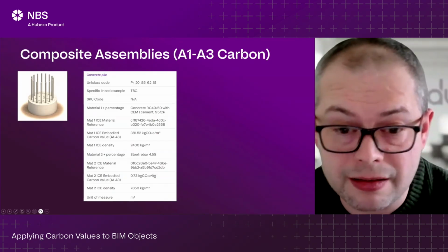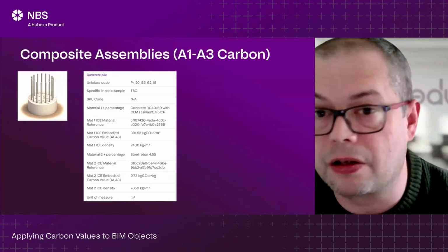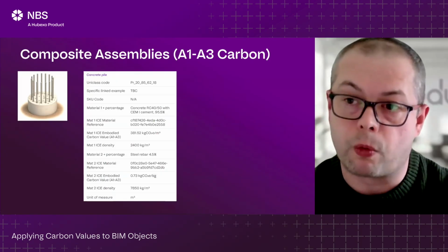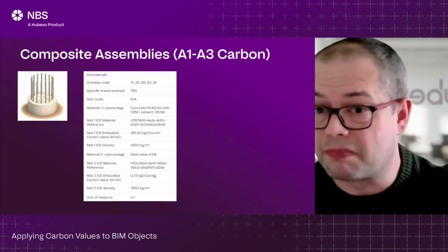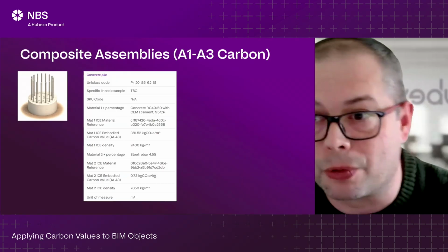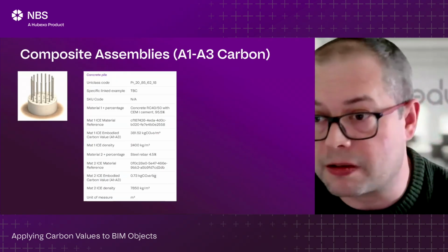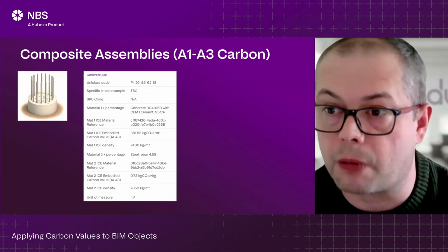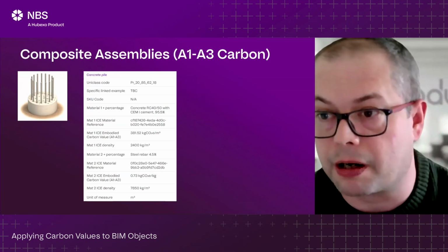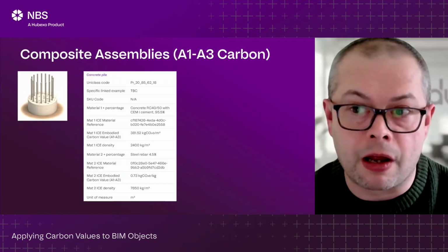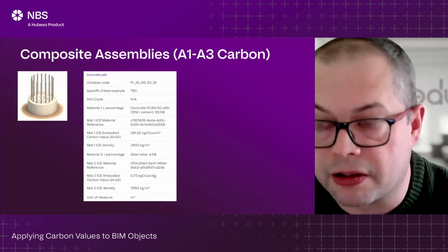And likewise with EPDs, if you're comparing manufacturer EPDs, you may compare one for one. One manufacturer, say it was a window, for example, may have had an EPD created per window unit. The next one might have done it per meter squared of window. So the carbon values won't always be directly comparable. You will need to do some calculations in terms of normalizing the declared unit values there.